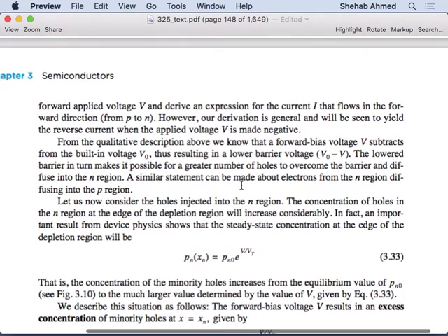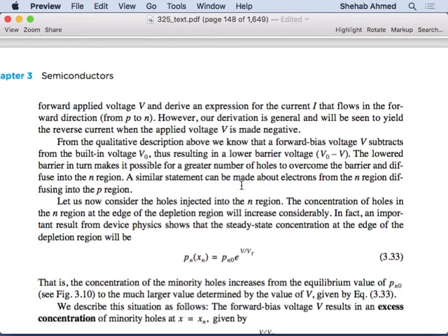But here, one thing I talked about. After 0.5 or 0.6 volts, we said that the diode will start conducting current, right? After you exceed the barrier voltage. But is this an abrupt thing that's happening? It's not. It's caused by the fact that you are allowing more diffusion to happen when you decrease the barrier voltage, right? But when diffusion happens, what's happening?